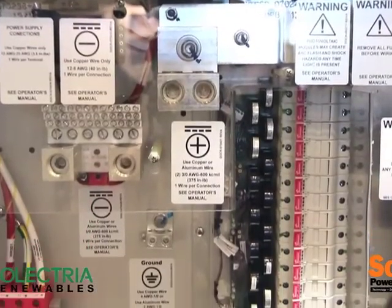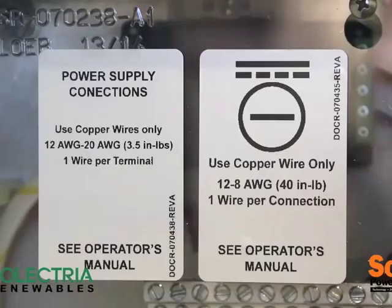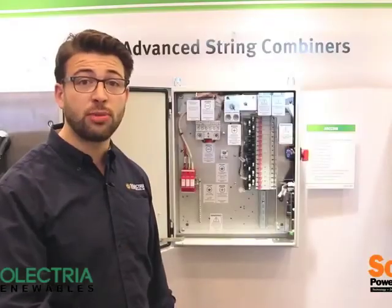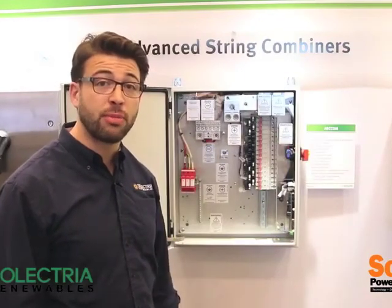There's DC current monitoring available in the inverters, such that when an arc is detected, the inverter is able to detect that the box is shut down, so you know to dispatch someone to site, look for possible damage, reset the box using the switch on the side, and then your system is back up and running normally.